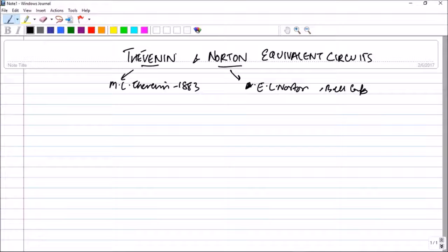So once you understand Thevenin's theorem properly, the generation of the Norton equivalent circuit is quite easy. Now, what is the motivation of Thevenin's equivalent? Basically, when you have a very complicated circuit and you want to analyze the current, voltage or power of only a part of the circuit or through a particular element, in that linear circuit, you can replace the entire circuit by a single independent voltage source and a series resistance, and you can keep the part of interest aside.